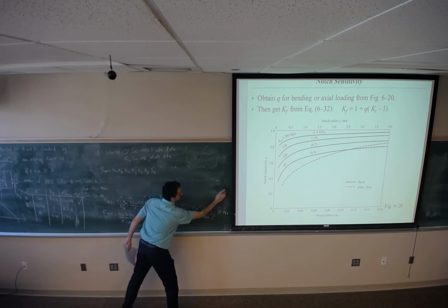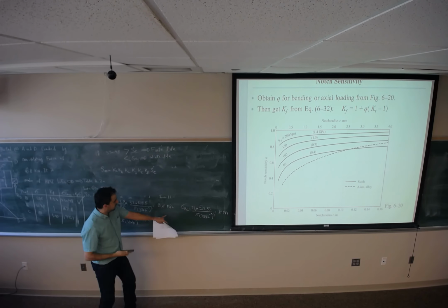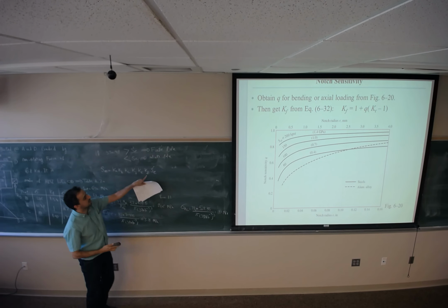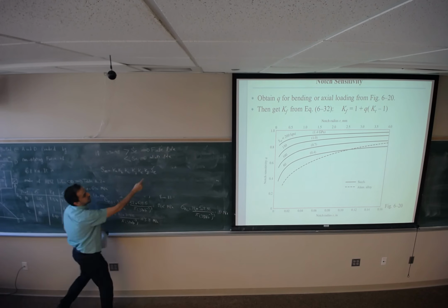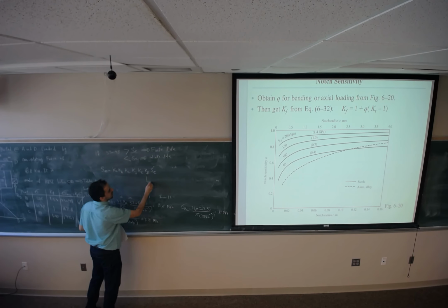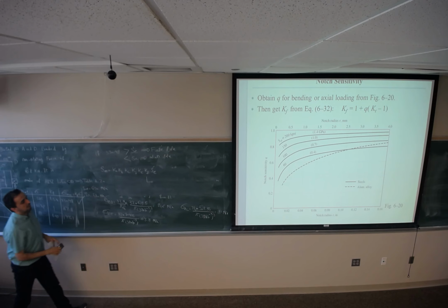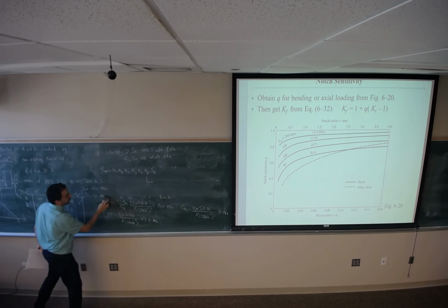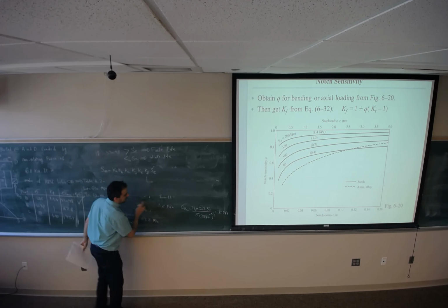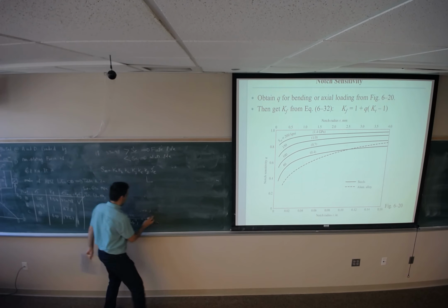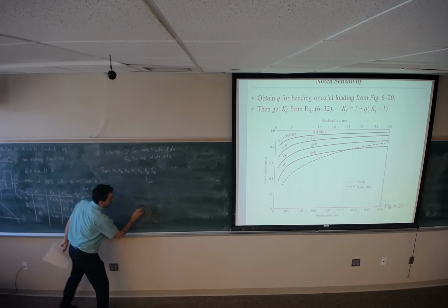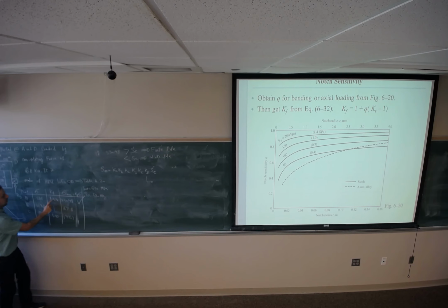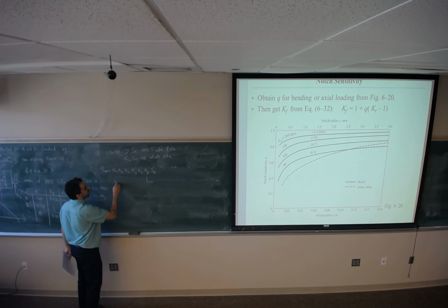This KF is different from that KF. I mean, don't be confused. That KF is the fatigue concentration factor. This one is the modification factor for endurance limit. It's totally different, so don't use this one on that one. So KA. KA was surface.